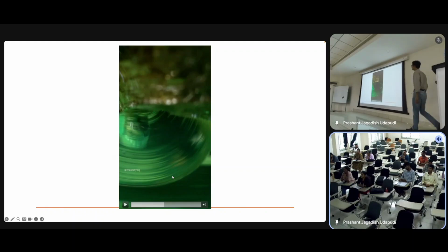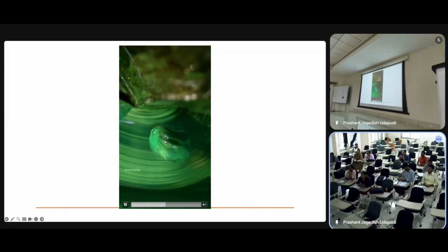This is even coming from the nozzle. This is where a big air bubble is coming through the nozzle even after forming, and it also depends on the solidification, based on the environment temperature. So this will create an even bigger problem.